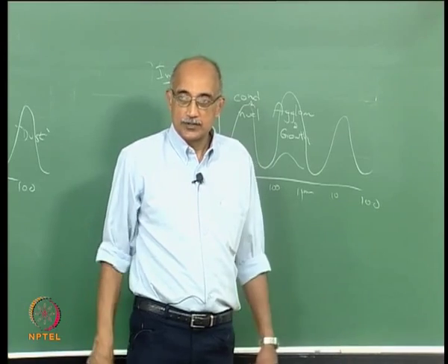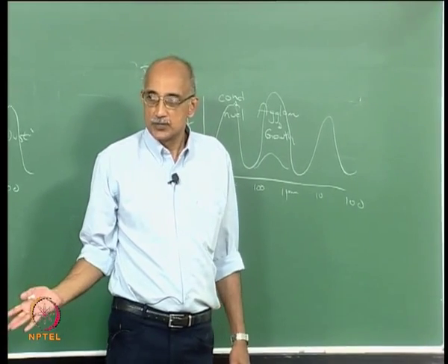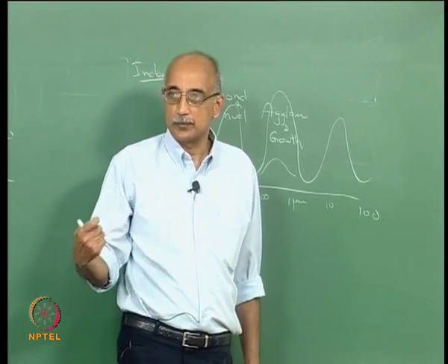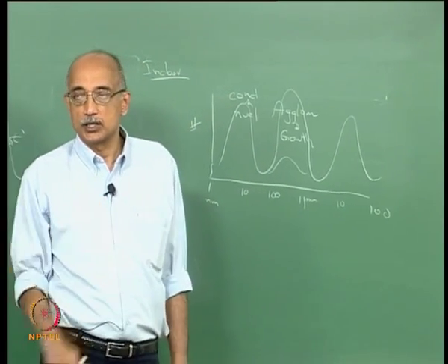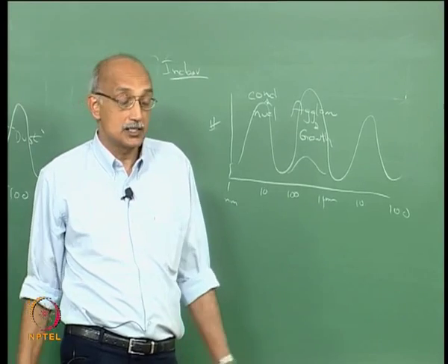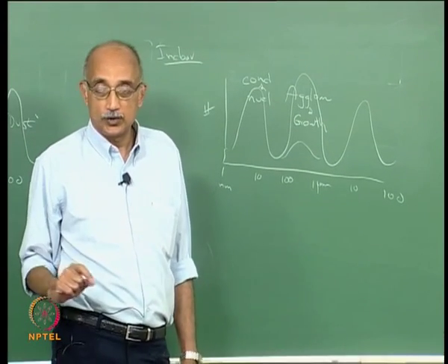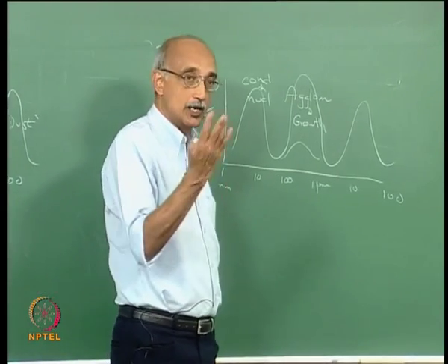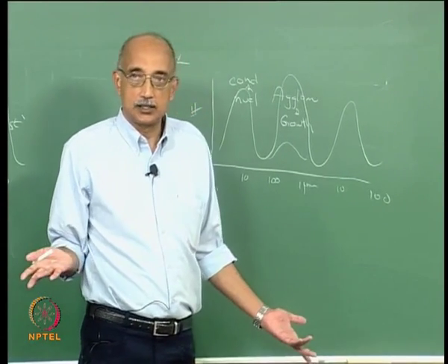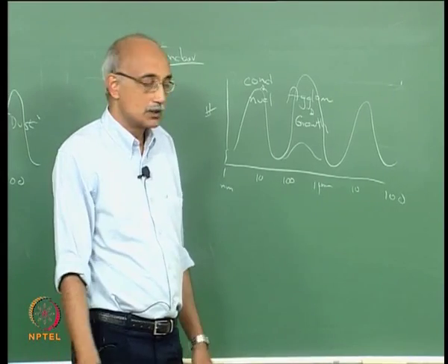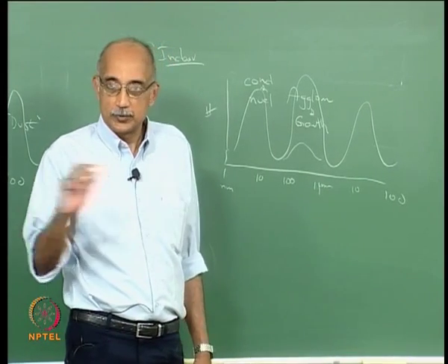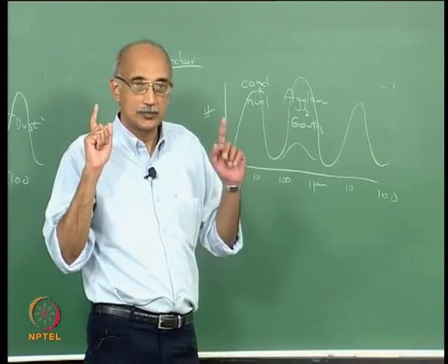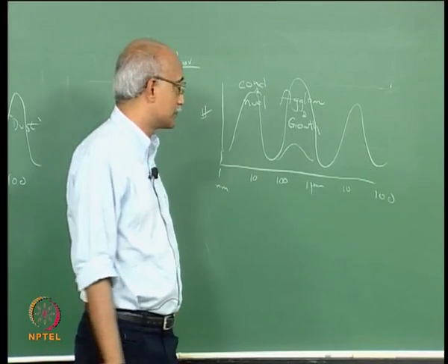This room, for example, just in terms of clean room classes, is probably about 1 million. And just to give you a perspective, if you actually took a particle counter and measured particles in this room, you will find there is at least 1 million particles per cubic foot that is half a micron and larger. Even though none of them is visible, you would think that this is a clean room, but it's really not. It's a clean room, but that's different from a clean room. It depends on whether you write it as one word or two words. Okay, clean room is something that is a very special thing.